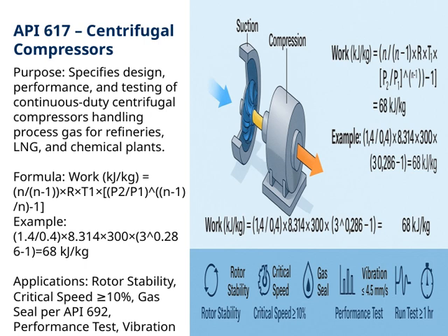Performance testing is essential to verify that the compressor meets expected standards, and vibration levels need to stay below 4.5 millimeters per second to avoid damage. Lastly, a run test lasting at least 1 hour is required to ensure reliable operation over time. Understanding these points helps us ensure that centrifugal compressors are safe, efficient, and reliable in their critical roles across various industries.